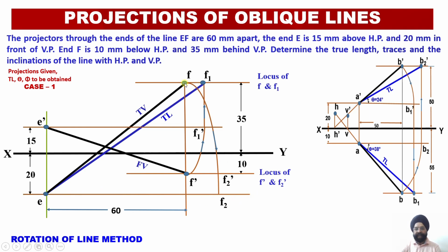So I'll open my compass this much. The intermediate barriers are not going to distract me, because if I end up over here, my projection in plan will not become parallel to the vertical plane. So I am focused on making this apparent length, that is EF, parallel to VP.